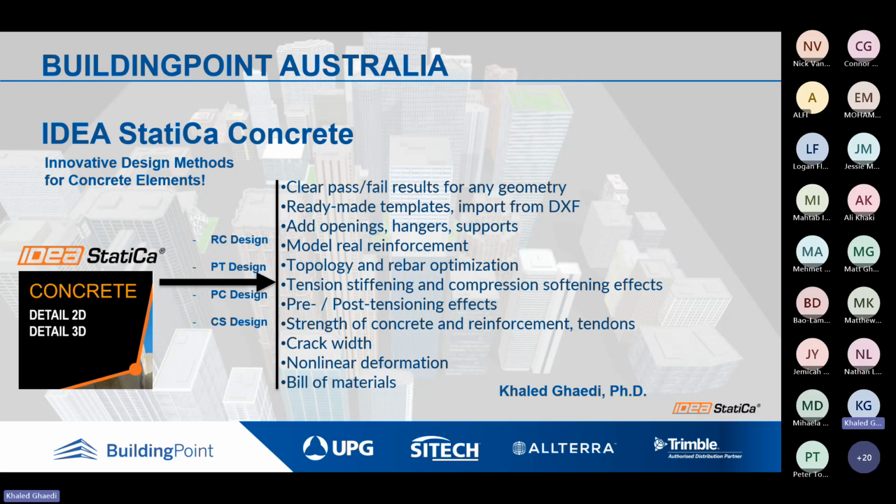In detailed 2D, first of all, you can bring any geometry or use the inbuilt template that we have in detailed 2D. You can create any geometry and edit the template, and you can go for different types of concrete material like conventional RC, post tension, precast design or composite concrete sections. And it is for ULS and SLS, or let's say for strength and serviceability.